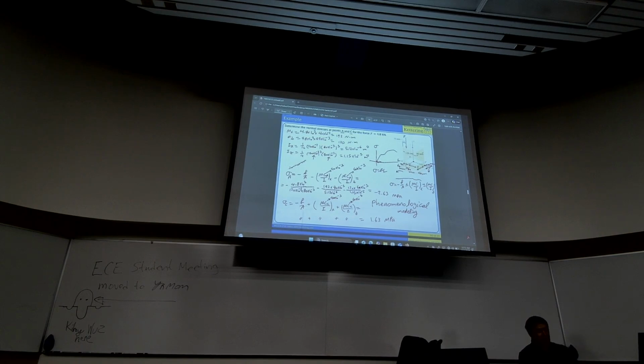He said, look at the data, I see that it's mostly linear. So I draw a line there, I come up with that slope, tangent of theta, let me call it E, the stiffness. And he said, okay, sigma equals E epsilon now is the equation. Instead of communicating all the data points, he says only communicate the E value for all of the points. So this kind of modeling, by just picking an equation by looking at the data, and then coming up with the constants that show up there, is called phenomenological modeling.